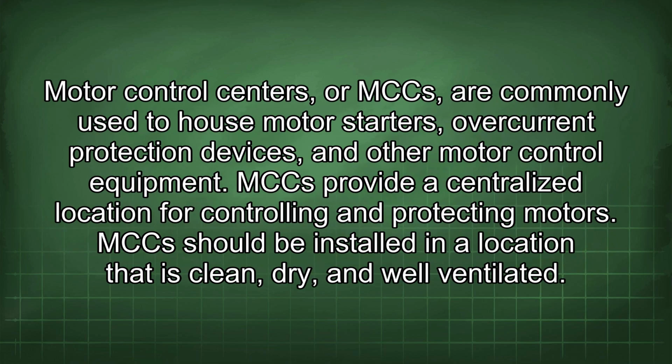Motor control centers, or MCCs, are commonly used to house motor starters, overcurrent protection devices, and other motor control equipment. MCCs provide a centralized location for controlling and protecting motors. MCCs should be installed in a location that is clean, dry, and well ventilated.